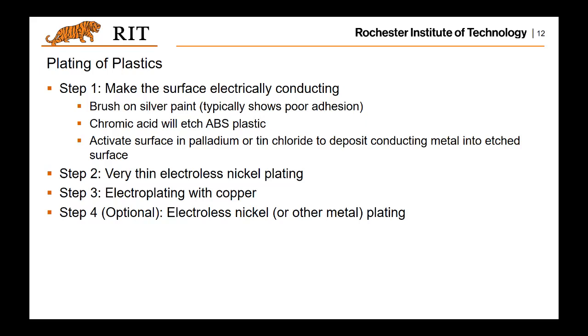Because the surface of the part has been processed to be electrically conducting, these nickel particles will be tightly attracted to the surface. Then we can electroplate with copper.